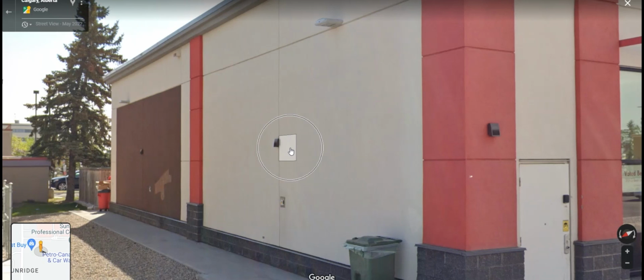And so back to this wall. This wall here was built with just non-combustible construction. So a steel stud wall, basically, with a steel superstructure, and the fire rating was put on the inside. Essentially, there's a couple of layers of gypsum board put on the inside to get the required fire rating.